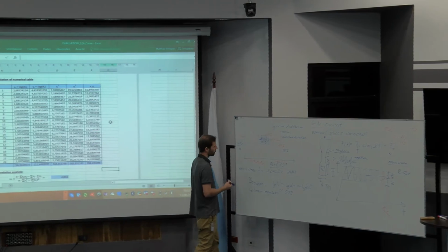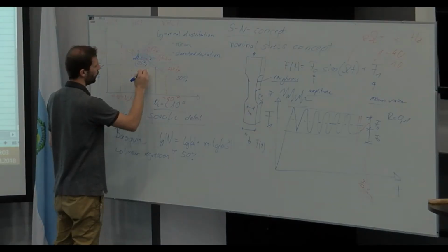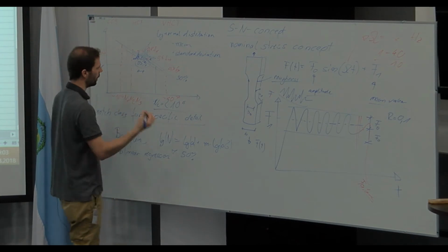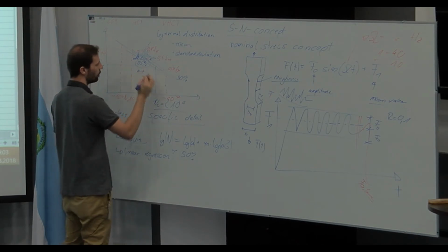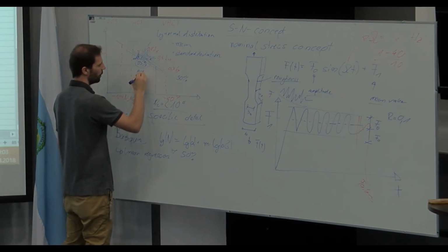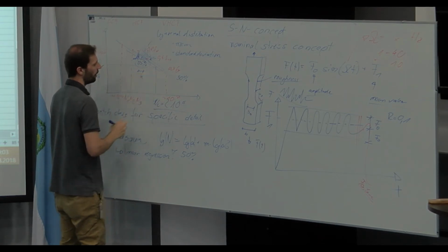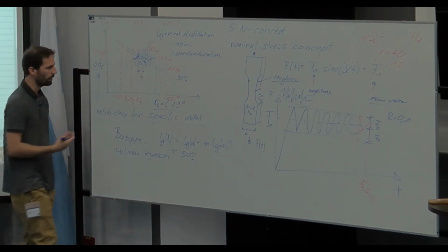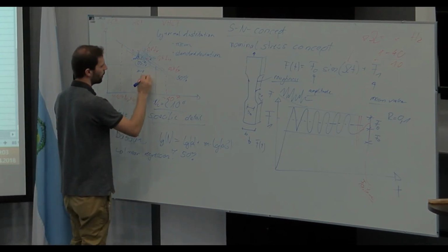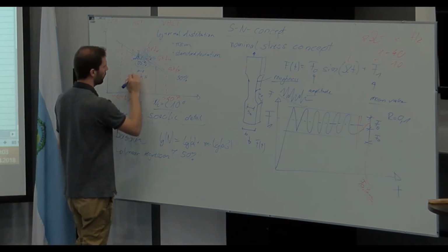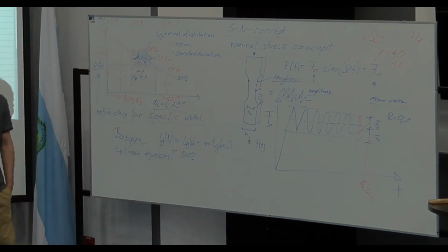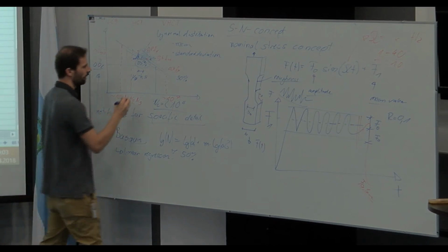So at this time we have to shift here also our mean value. Usually you have to define a value k, which depends on the amount of specimens, times the standard deviation, and here you have the 50% value minus, so the mean value minus k times s.